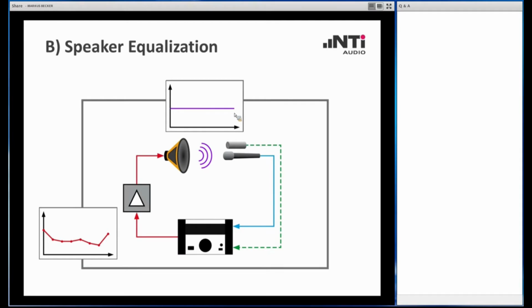This looks simpler than it is. Keep in mind, this is a bit of a demanding procedure, but it is feasible if you have high quality devices in your setup. And now we can, of course, directly measure the frequency response from our microphone here, the one we want to test, and we get the same response as in the setup before, but now we get it directly with a direct measurement due to this linearized, equalized frequency response from the reference speaker. Once again, keep in mind, this is the more demanding approach. It requires high-end components, a high-end reference speaker, and a thought-out calibration routine to get to this point where we have linearized the frequency response.